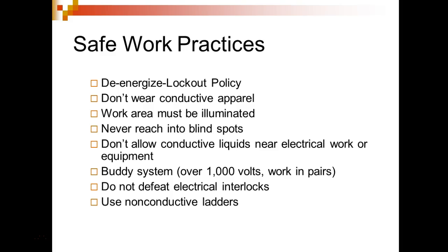But what you're supposed to do on a tag out is put who the tag belongs to, and then basically how to contact them. A lot of times there is a section to put the date the tag is put on, but as far as I know, that's not required. What is required is the name. At my first job where I had to use lockout tagout, we actually had individual tags. You couldn't attach it to the lock. It had to be attached adjacent to the lock, so that if somebody else had a lock on there, the tag stayed with the equipment.